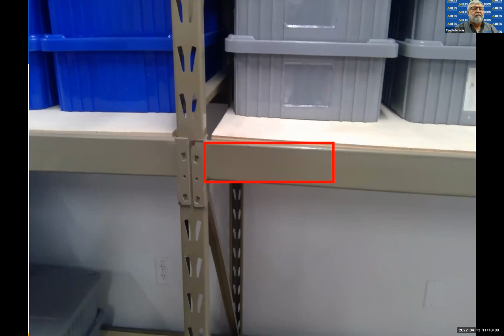I've investigated some very, very serious accidents over the years. One fatality because a racking system was overloaded and it ended up taking a person's life. So how does that operator or that employee know how much weight to put on it? Well, it needs to be labeled. OSHA's looking at it. Is it 500 pounds per rack? Whatever it is, is it placarded and is it noticeable? And do we train our material handlers to make sure they understand that overloading that rack is very, very dangerous?